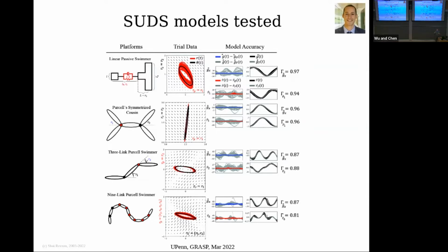So this data-driven way of learning the connection works, learning the body velocity as a linear map of the shape velocity as given by these 2 motors, even though there are all these other passive degrees of freedom. So it suggests that learning how to move with underactuated flexible bodies is actually a lot easier than we previously thought, as long as you're friction dominated, as long as you're overdamped.